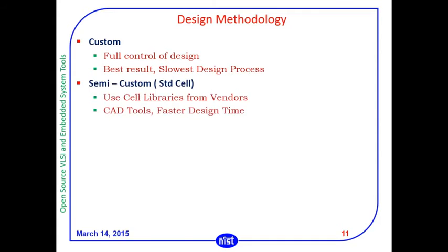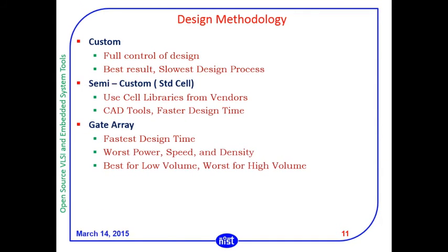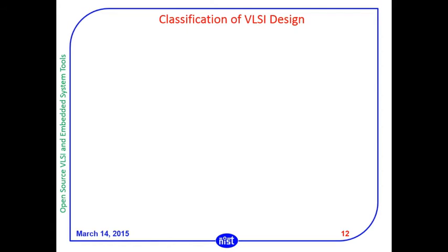Semi-custom: standard cells, gate arrays. These are a few designs. Out of these, PLA, PLD and all that, basically we will be using the custom method, where the design is full control of design, best result, slowest design process. That's true, but in this course we will be learning the custom design methodology. We are not going for semi-custom, gate array and all that.